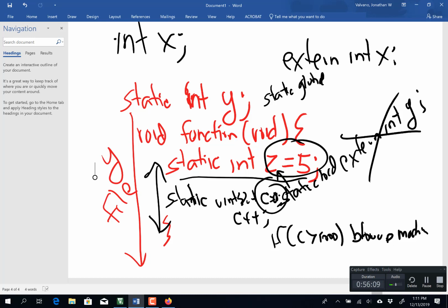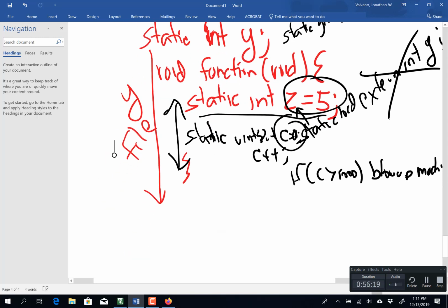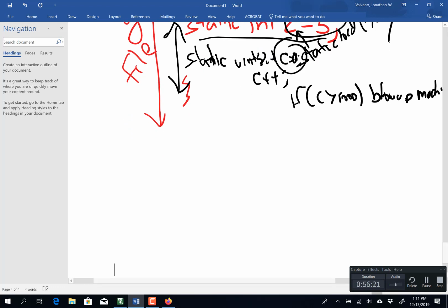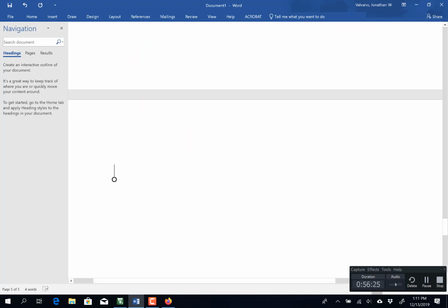All right, I know you've got lots of questions. So what we normally do, like in Lab 5 for the SysTick, is that we put the reload value, we cleared the current register, and then we checked bit 16 of the current register, so we know that it has not yet come to 0, that it hasn't finished counting.